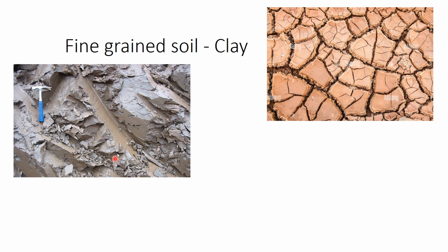It will swell and it will affect the structure. And when it shrinks, when it loses water, when it dries out, it undergoes shrinkage. Again, because of this shrinkage also, it will cause some distress to the structure. So the swell-shrink mechanism of clay is a very big issue, which needs to be addressed when we are going to have it at our site.